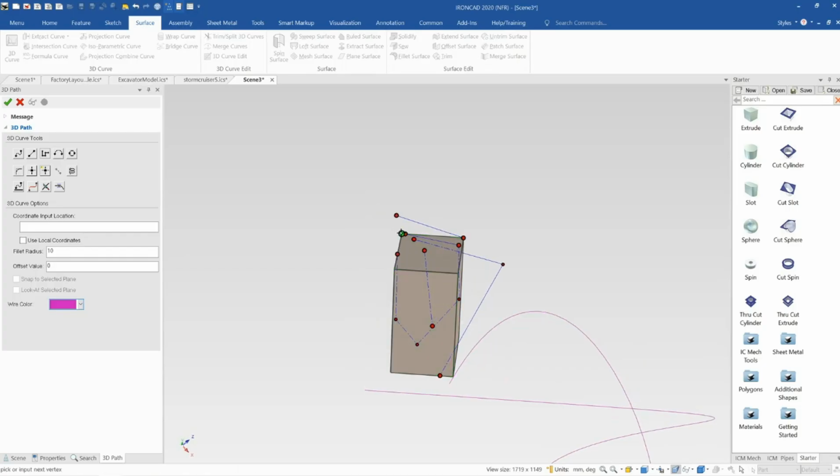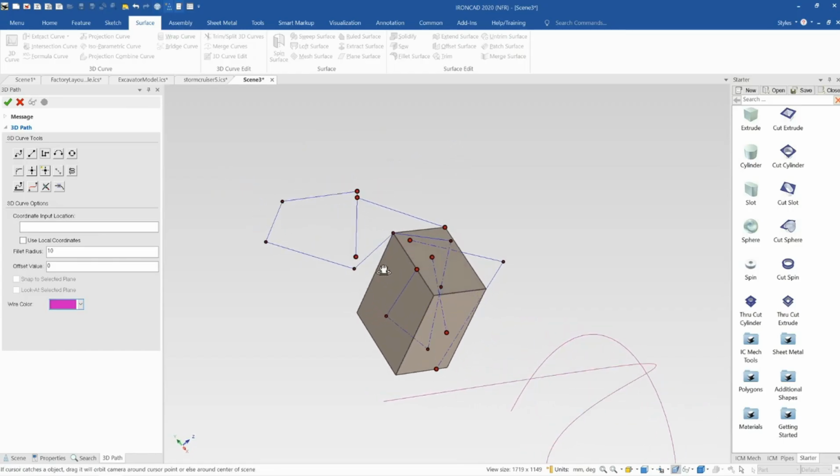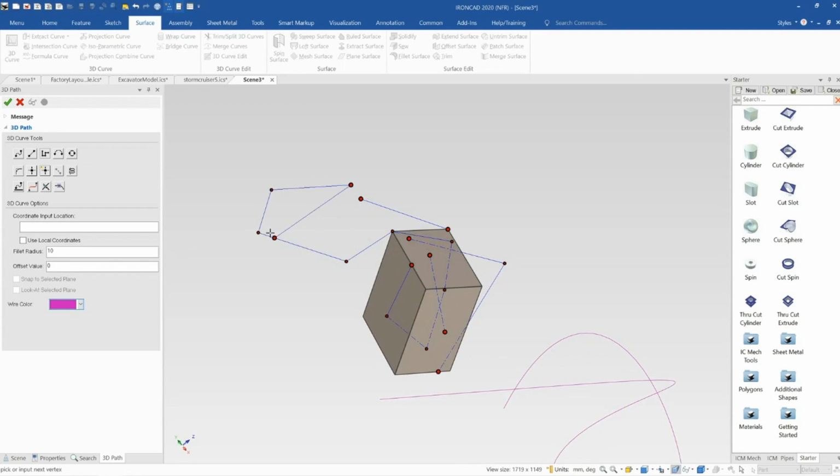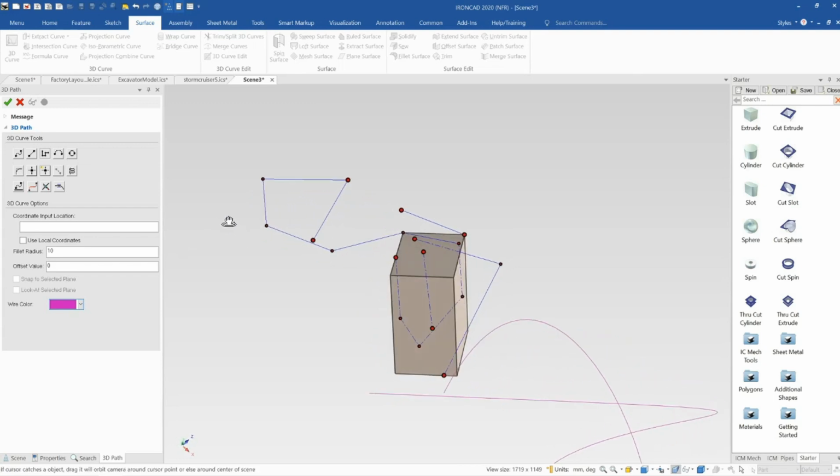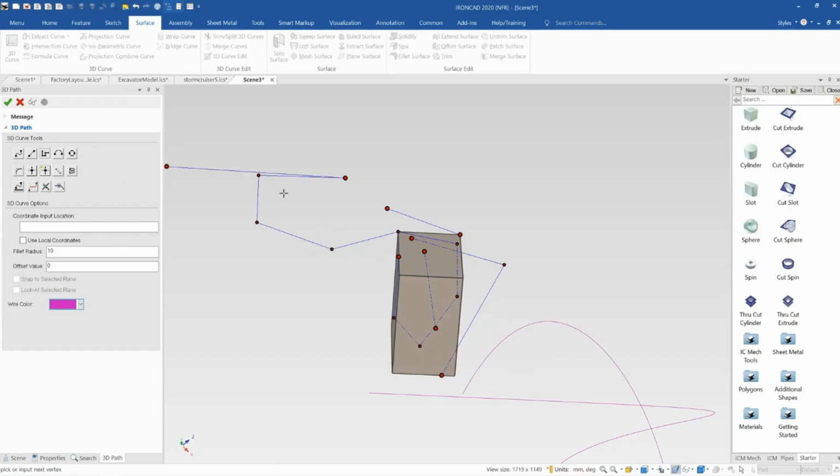And it's very useful with the polyline option to use the tribal, because you can again use the P key to place points. So place a point here and drive off over here, place another point, and you can see we're now creating a 3D curve between multiple stops there, which is based on all straight lines or straight sections, which is great for doing steel or piping, for example. So this is how we create the factory layout piping option.